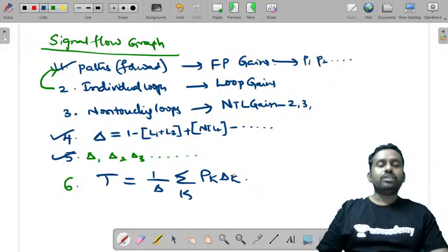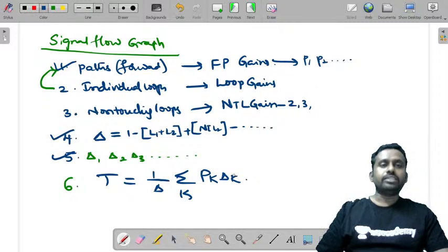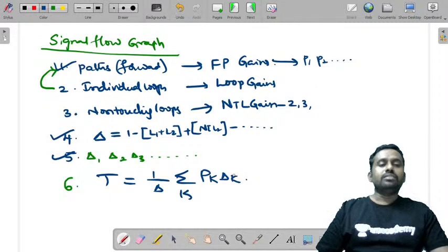Now what will you do in that case? Without doing anything, if you try to design it, and the fan does not meet the expected outcomes given by the consumers, then it would be a waste of energy, time, material and cost, everything. So before doing that, first we'll try to find the transfer function, then we'll analyze it. This is not only in the case of very small things, it's also very important in very large machineries or manufacturing units. Knowing the prior information, finding it or simulating it, finding the transfer function, knowing its responses and adjusting the values to meet the desired requirements.